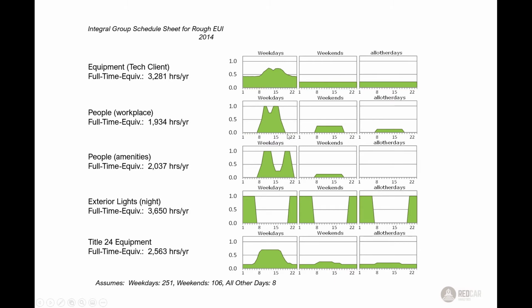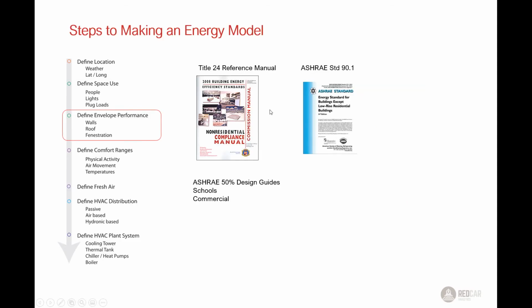To give you a sense of schedules, I talked about this a second ago, but with each one of those space types, there'll often be lots of different schedules that represent perhaps equipment in the buildings. So you can see here the equipment coming on, and they're usually fractional, 0 to 100%. And we can see then on the weekends, the equipment is off, not as many people. And here you actually see a different equipment schedule. This one represents actual people and their body heat coming in. So these are all also inside these reference manuals.